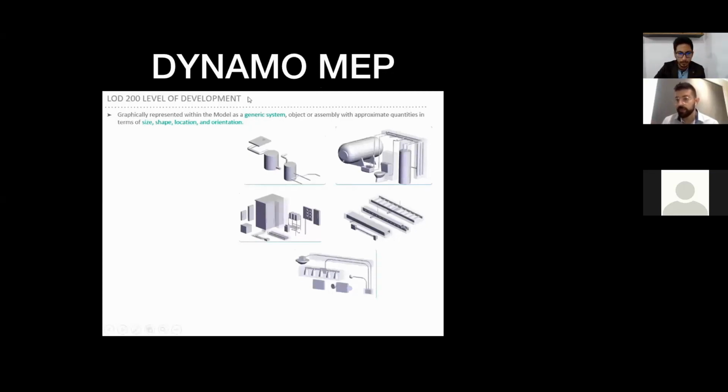So perhaps my best recommendation would be to start by creating nodes. Maybe it will become efficient. Use a node to code option, and with that start learning how to code it by commands on design script. If there's something that Dynamo cannot do, I recommend you check on Google if someone has created a similar node. If they haven't, now you can get into the terrain of using Python